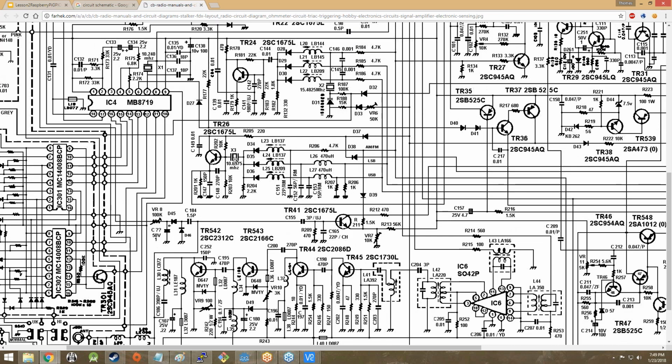And so something like this becomes immensely useful because then you can go, okay, so let's go ahead and trace this wire right here. This is going to go here. All right, so it connects to a couple of other things. Let's keep going. All right, so it hits this transistor here, and then it comes into pin 12 on IC302, MC14008 or 14008 BCP. Cool.